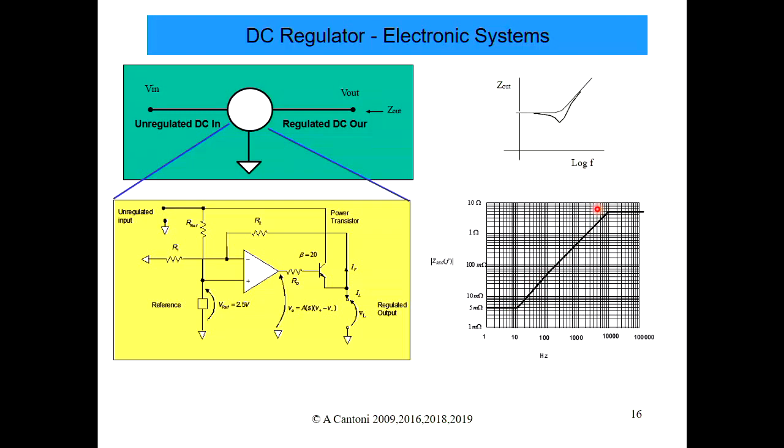You mean like an RL circuit? It'd be an RL circuit, right? So it'd be a resistance here to represent the low frequency, then an inductor in series would be a good model for that particular regulated circuit. And in fact, that's what you see in the project. You'll see that the model for the regulated power supply is a resistor and an inductor, plus an ideal supply, right?